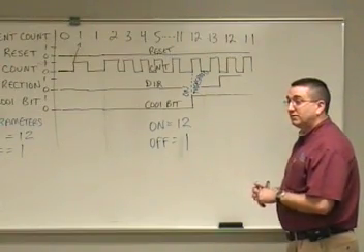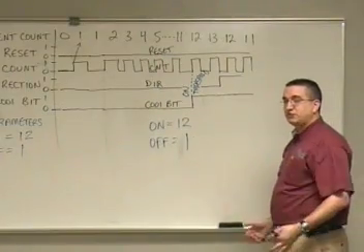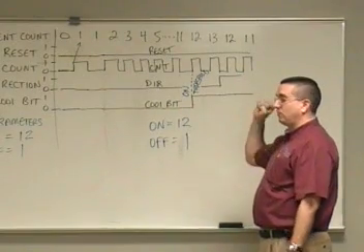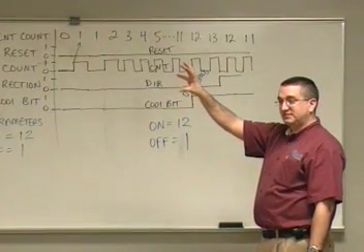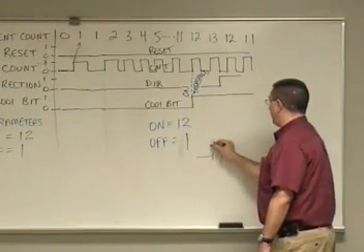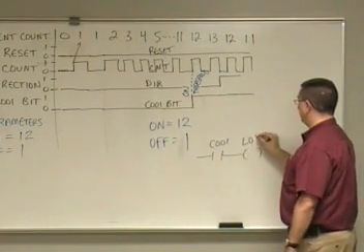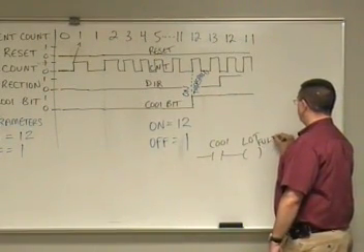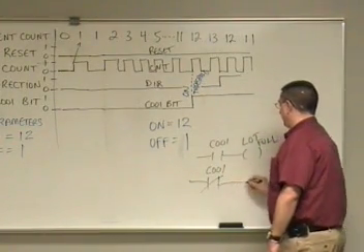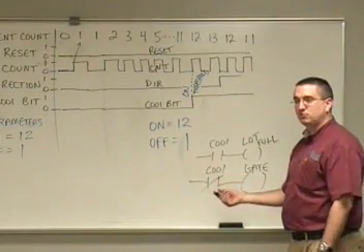As an example, the parking ramp. The lot holds 1,000 cars. I get to 1,000 cars, I turn on the C001 bit, the C001 bit lights up a light at the entrance that says lot full. And maybe the C001 bit lights up that light using a normally open contact. Okay, there's my light, lot full. But maybe it also breaks the ability for my gate to be open. Maybe my entrance gate will not open when C001's there.